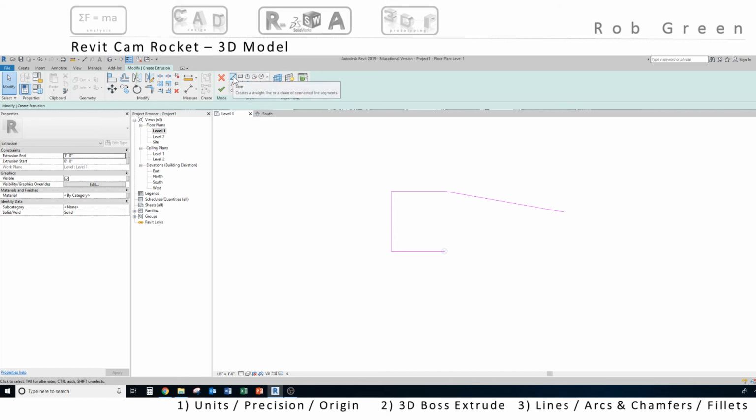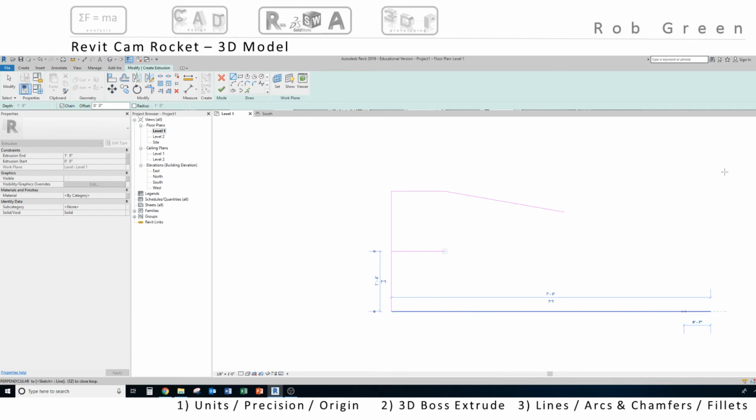So I'm now going to draw the bottom left portion of the part, and I'll use the line command. I'll come snap to the left-hand point, come down 16 inches, and I'll key in 16 inches, click enter. Then I'm going to go again to the right 84 inches, press enter, go up 40 inches, press enter, and go left 29 inches.